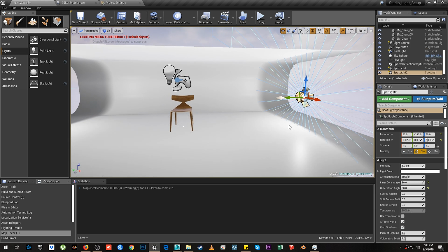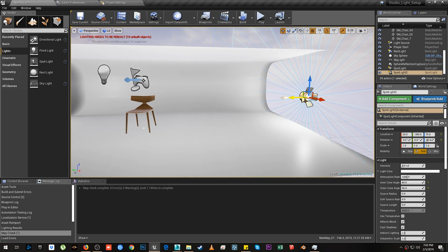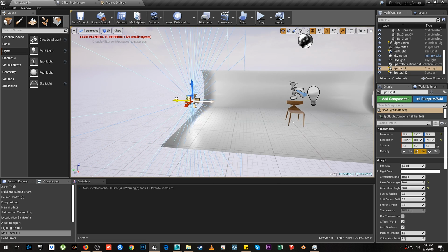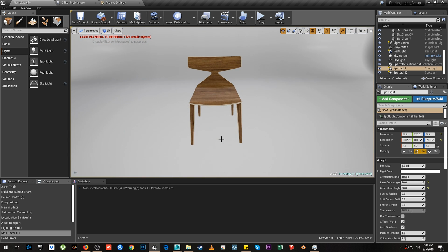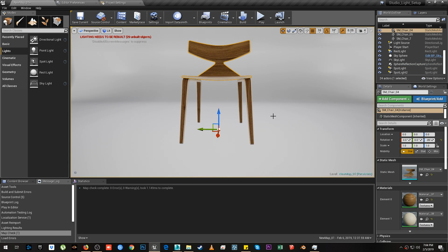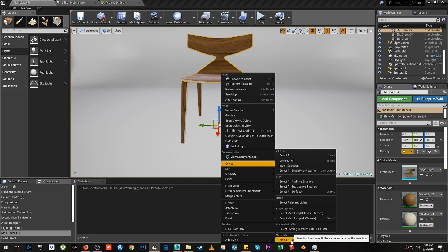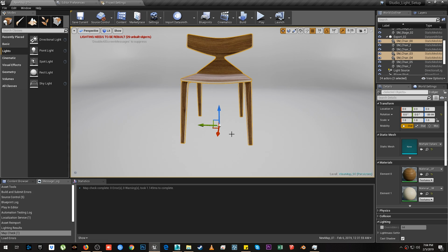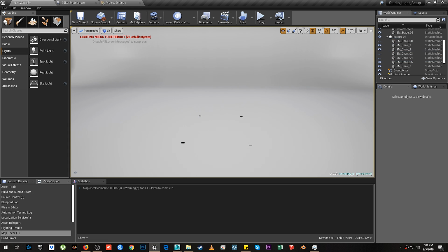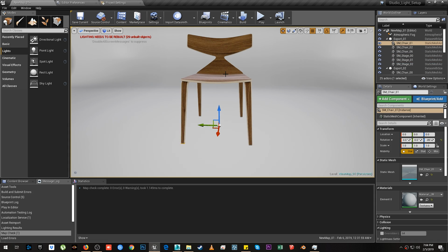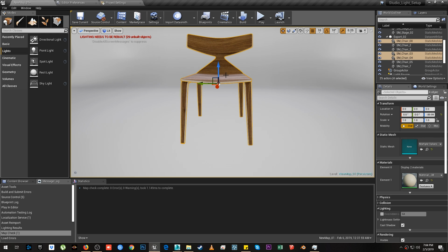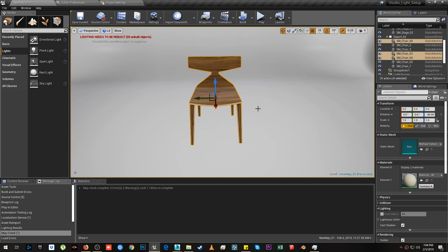And I'll go here and bring these lights to the edge. And then I will right click and select all the materials, and then I will press Ctrl G, then hide, and then select this, and then Ctrl H, and then I will press Shift and select this chair, and then again press Shift G to explode, and then Ctrl G to attach it.